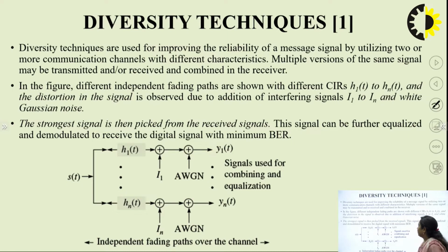Diversity techniques are used for improving the reliability of a message signal by utilizing 2 or more communication channels with different characteristics. So what do you mean by diversity technique? It is a technique which is used in multipath propagation. Let's say there is one transmitter and one receiver, and no direct line of sight exists between the transmitter and receiver. So this particular signal has to propagate from this terminal to this terminal via different paths.